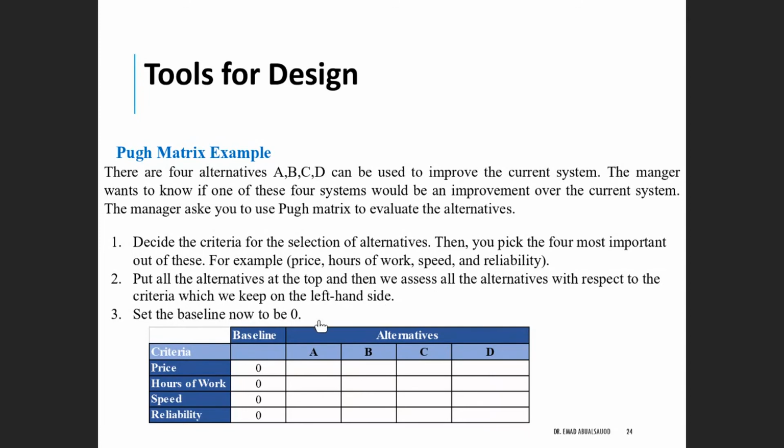And you put all the alternatives here on the horizontal line, and you start assessing each alternative against the criteria, comparing to the baseline. Now, whether you compare it to the baseline or with another product depends on your case and the design. And for this example here, they were comparing against the current system, and they have now multiple systems or alternatives. They could replace it with their current one, and they would like to evaluate those alternatives compared to the one they have now.